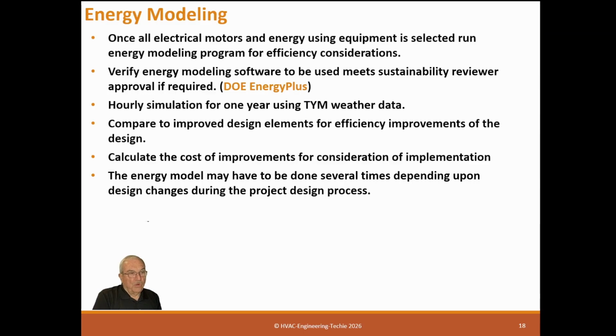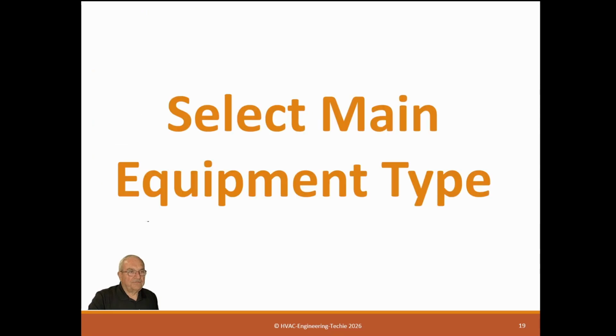Now, most people don't use load calculation design software to do energy modeling. They're two different things. You can kind of use what I call an integrated load, like if you're using TRACE. You can run an energy model on TRACE, but it's not really the same. You really need to use a piece of software that's designed specifically for energy modeling. Energy modeling software is not really as detailed and robust as the design software, but they're doing two different things. That's what I'm trying to say. The design software is trying to figure out what the load is. The energy modeling is trying to figure out how the load actually operates. So there's two different things.